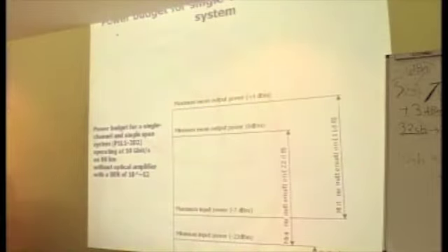And we need some power for optical path penalty, 1 dB or 2 dB, above this receiver sensitivity level. So we call this the minimum input power we require. This is just an example of our 10G 80 kilometer system. And the criterion is, as I said, a bit error rate of 10 to the power of minus 12.